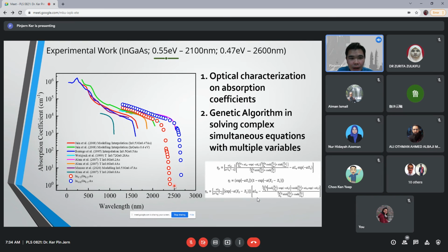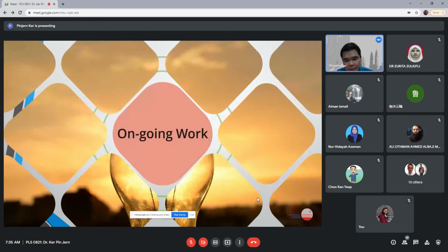Currently, honestly, we don't have a real, optimized TPV cell at this particular wavelength. But from the fundamental characterization and the absorption coefficient, we can easily do a back calculation and say what is the possible efficiency if we are able to grow at a certain thickness and a certain doping and so on. So this was another work done, to be published later on.